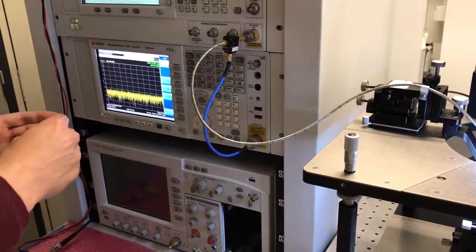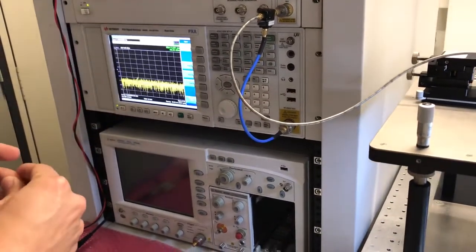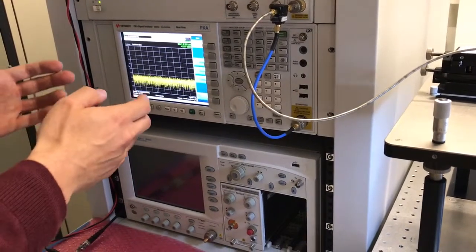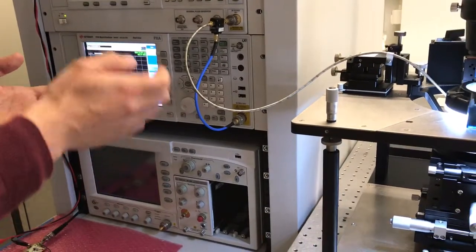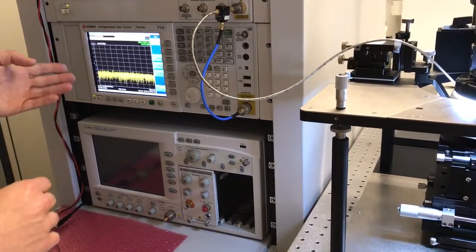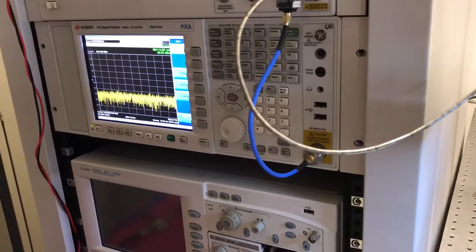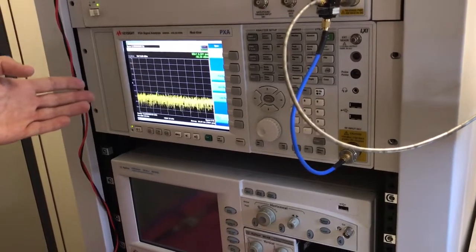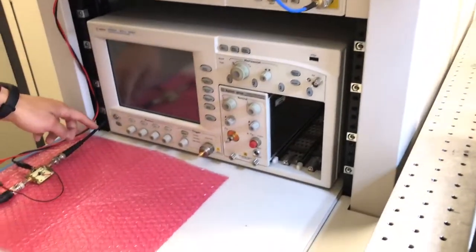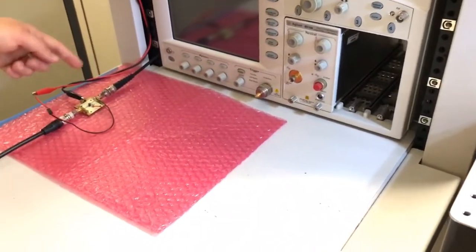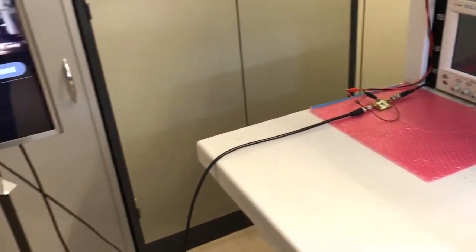The signal analyzer is actually working as a down converter. So it is converting the 13 gigahertz signal to an intermediate frequency. In this case, the intermediate frequency of this equipment is 322.5 megahertz, and it's a connector on the back of the equipment. So we have an RF cable connected on the back of the equipment that is coming here, and through an amplifier that is right there, it's connected to the TV.